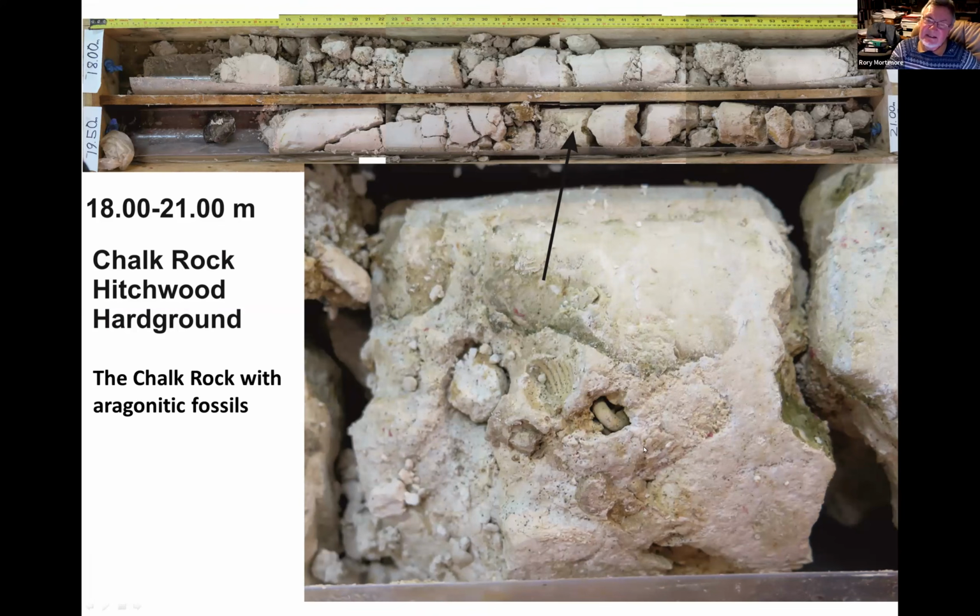And the aragonite has dissolved away and the carbonate has cemented this into a very hard rock band. So these are very high density layers. And actually, where these are present, particularly if you're piling into them, particularly in the offshore piling industry, these are surfaces that require pre-boring rather than being able to drive your pile straight into it.